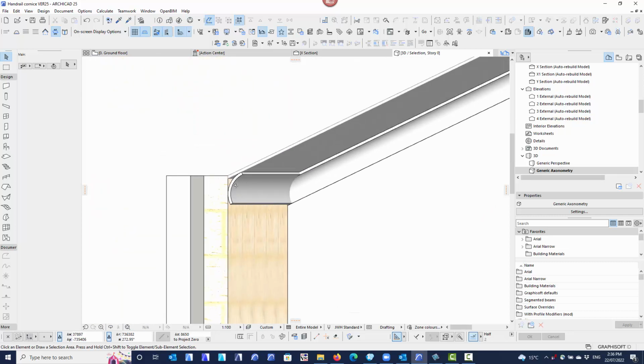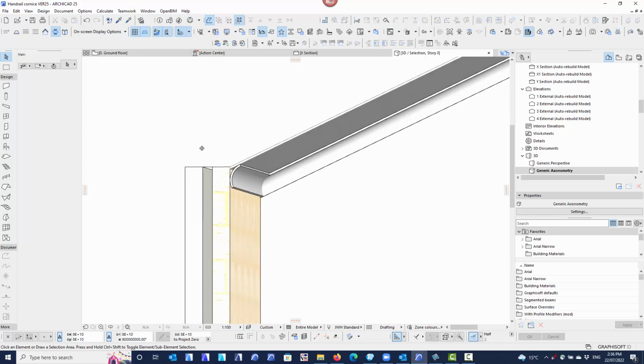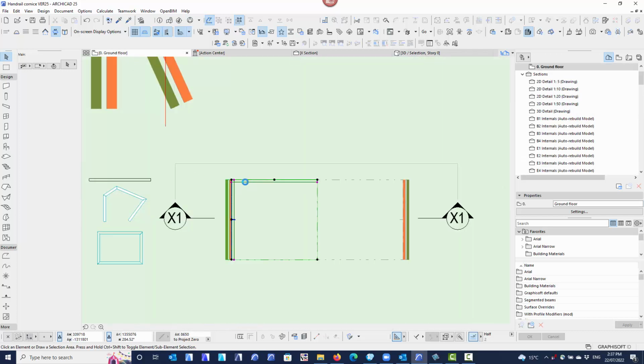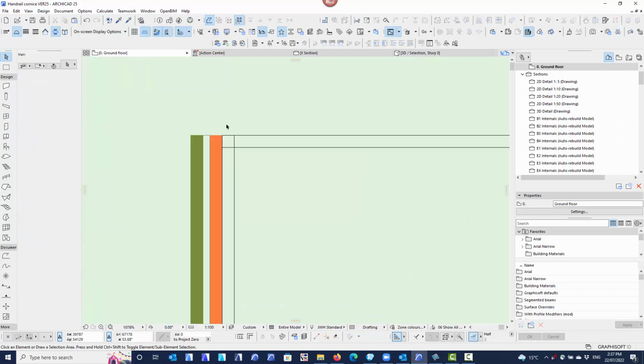You're much better off to use probably a different cornice. The one that works quite well is the Gyprock Classic Cornice. That's quite a nice one for raking ceilings. So if I go back to my floor plan here, we've still got the cornices in the right location.